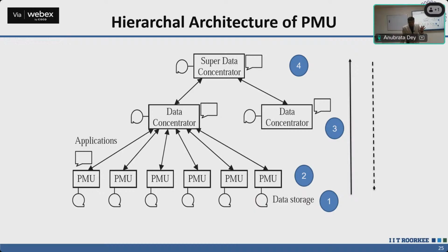So what are they doing? I visited one PMU station near Delhi, at NLDC. There, they mark some important flags on the PMU data. Let's say these are events which are very important, and for those events we need the data. So they flag them. Whenever the overwriting of data takes place the next day, the flagged data is not overwritten and remains separately. That is what they are doing.